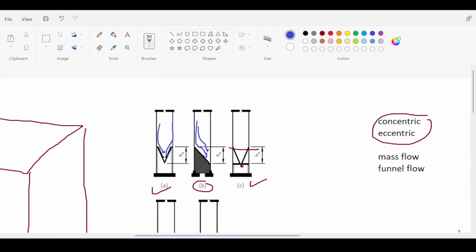Imagine, as I explained just before, you have a silo that has a horizontal opening, for example here. When you open this opening, the granular material will start flowing out. This would flow out easily. This will flow out easily. This will flow out harder. And you can see it's because of the tangent of the expected flow profile. If the tangent is too shallow, the friction angle will win this battle, if I may coin this term, and the friction angle will overrule the flowing tendency of the material, which means that you have static material here.